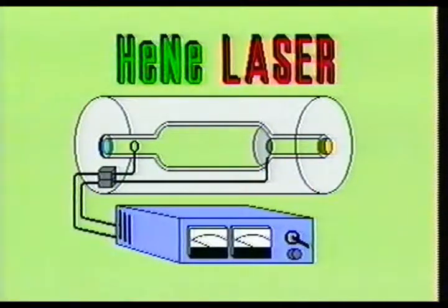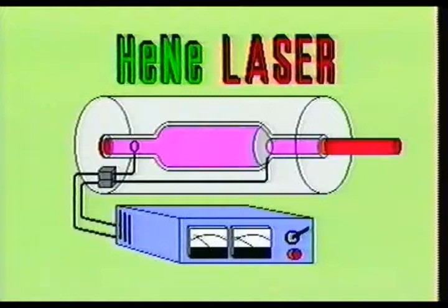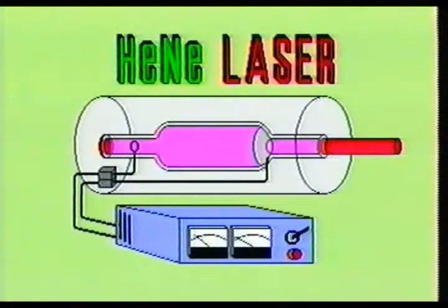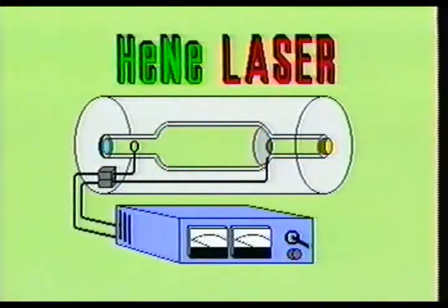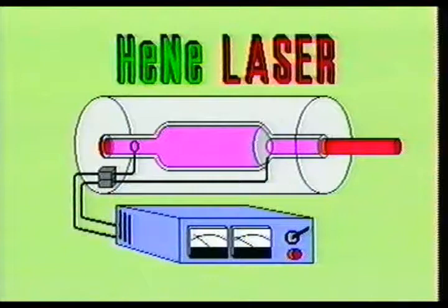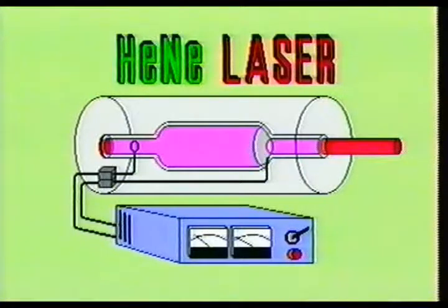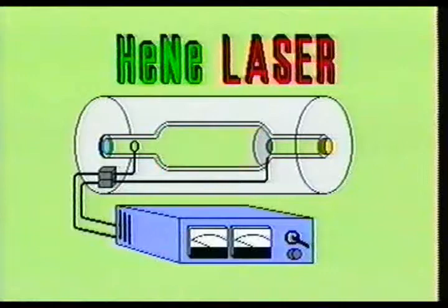When the laser is first activated or turned on, the HeNe tube receives an initial ignition pulse of 10,000 volts, which breaks down the gas molecules and starts the laser operation. When the gas becomes ionized, the HeNe tube will conduct a current flow of only a few milliampere and maintain a voltage of 1,000 to 2,000 volts. The electrons in this discharge path will raise both the helium and the neon atoms to their excited states.